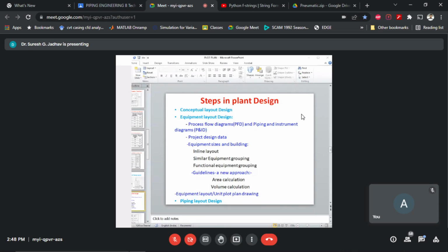Columns can be lined up to have a common platform for manholes and valve operations. Reactors or agitated kettles can be grouped to have common operating levels and lifting beam for the agitators. Utility equipment is normally housed together for operating convenience. Process compressors under one roof are a frequent requirement. Pumps in a row can facilitate better rack layouts, cable arrangement, and maintenance accessibility.